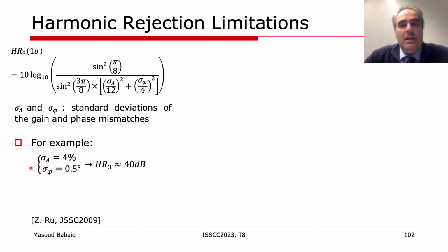For multi-phase clock generation, it is common to use high-frequency master clock with low phase noise to provide the input clock for a frequency divider. To remove the random jitter originating from the frequency divider and reduce the phase mismatch among the generated clock phases, it is crucial to retime the multi-phase clocks with the master clock.